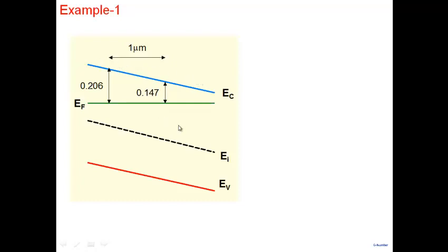All right, what else can I get? Constant field. What is the direction of the field? Right to left. Okay, what else can I get? What else can you get from here? All right, so let's see. Equilibrium. Yes, everybody agrees. P-type. Is it P-type? Why? EF is always above EI. Everywhere. Note that EF is always above EI, which means everywhere in my system electron density is larger than intrinsic carrier concentration. Okay, N-type. Uniform N0? All of you have argued, no, it's not uniform N0.